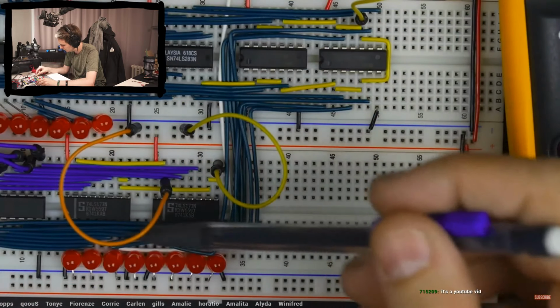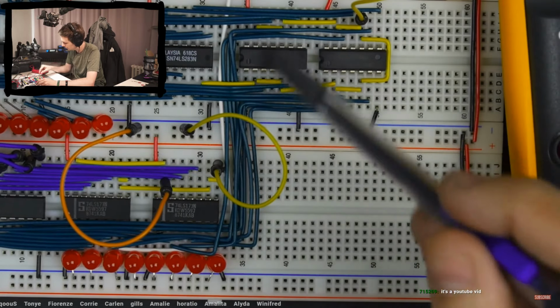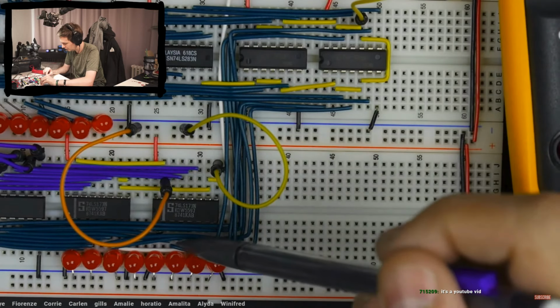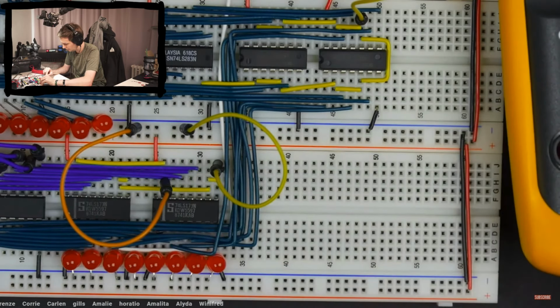Yeah, so this is the B register down here, and you can see these wires that kind of go up here are going up to our XOR gates, which is part of our negation logic that goes into our adders here. So I think the easiest thing to do is probably just down here, where we have our third and fourth bits connected up to here, just to swap these two wires.